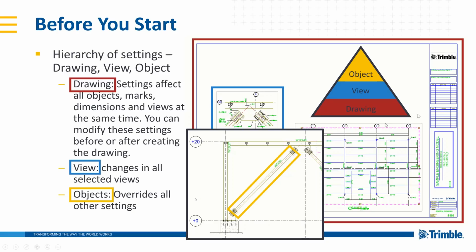Okay, so I have all of these settings for the drawing and the view specifically because I don't want to have to go through and make all of these individual changes on the individual objects. And so by creating my drawing settings and my view settings, sometimes it may be time consuming, especially if you're just starting a new project with a new client or if you're starting Tekla altogether. Some of these may be a little bit more time consuming, but the idea here is that the next time you want to go create a drawing that looks like, say, this plan view or a detail sheet, all you have to do is select that location in the model and populate a sheet with that view. Your settings are already created, and then the additional work that you have to do is minimal.